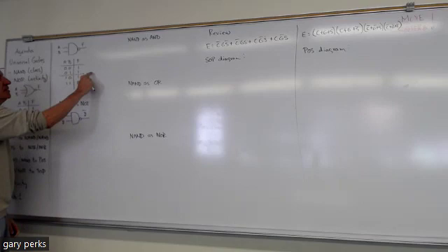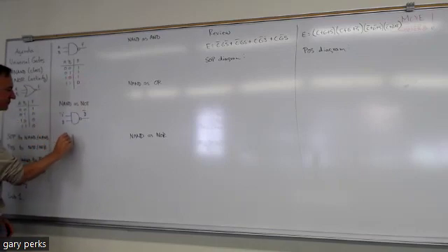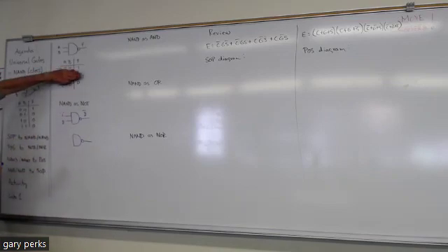There's a second way that I can connect a NAND gate to be a NOT gate. Just look at the top row and the bottom row, and ignore the middle of the truth table. In the top row, if I make both inputs 0, the output is going to be a 1. In the bottom row, if I make both inputs 1, the output is going to be 0. Well, that's a NOT gate, right? You're getting the opposite out of what you're putting in.